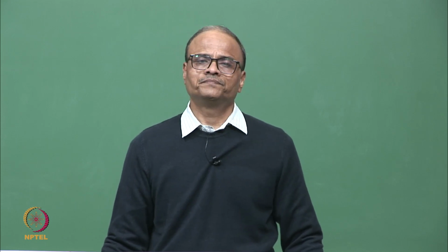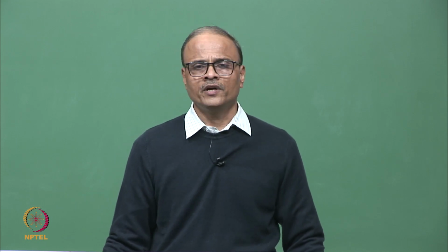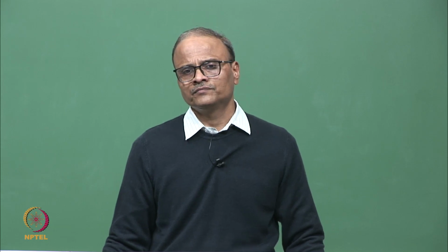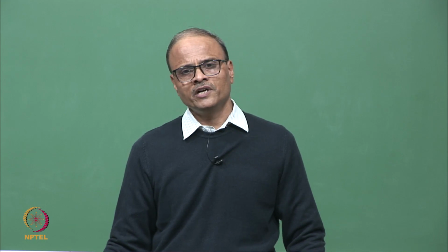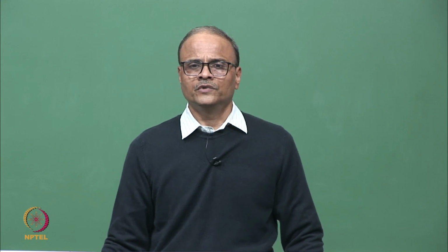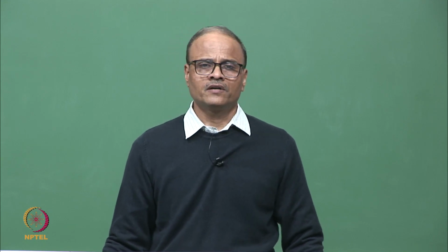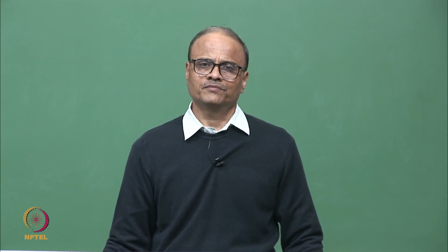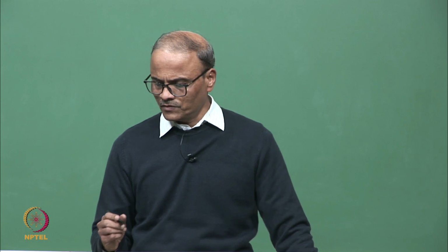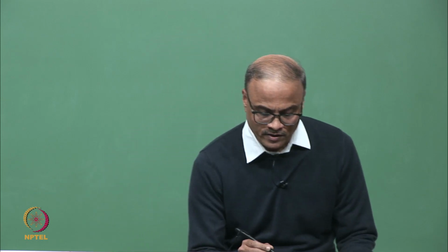We will look at anti-resonances for a point and transfer FRF. We will look at why anti-resonances occur and how to estimate anti-resonances. Then we will look at the FRF characteristics for multi-degree of freedom damped systems. Okay. So therefore, the topic today is